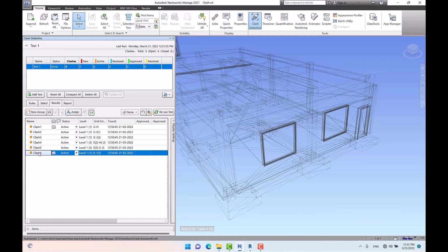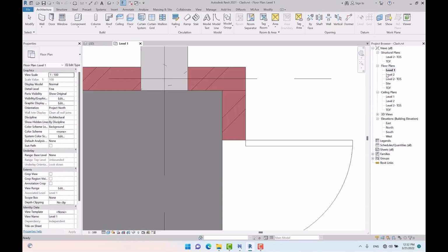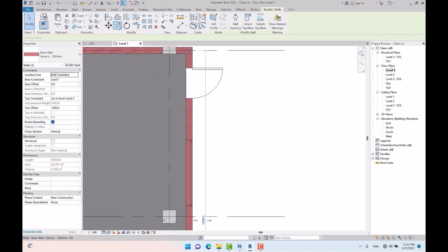I modify the value of tolerance to 1 meter, and as you can see, it has no influence on the clash detection, since there are no copied objects within 1 meter distance. Here in Revit, check this out. I'm gonna give you the last example for the duplicate.